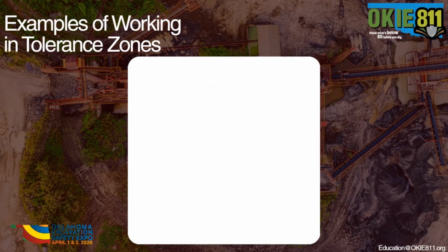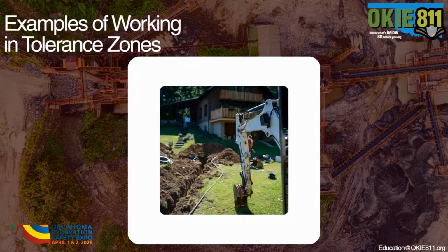Here's another example. So another team is trenching to install fiber lines. They practice soft digging, expose the utility directly under the marks, and they maintain soft digging and did not use heavy equipment around the tolerance zone. As such, they did not have any strikes. So being able to expose those utilities, visualize, having the concept of my lines might be running next to theirs, and having space to differentiate that.